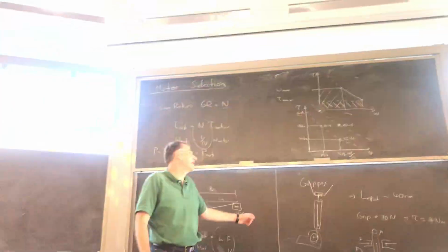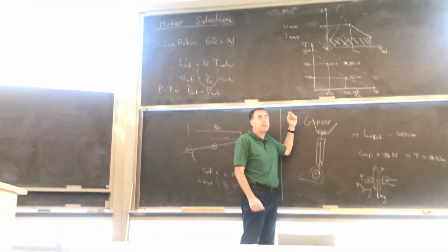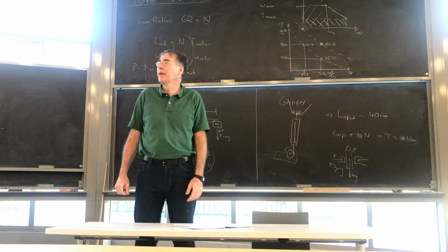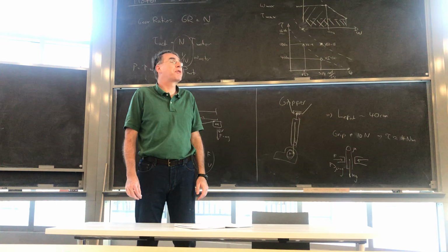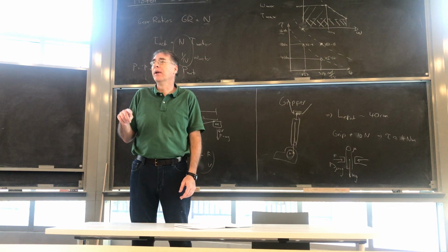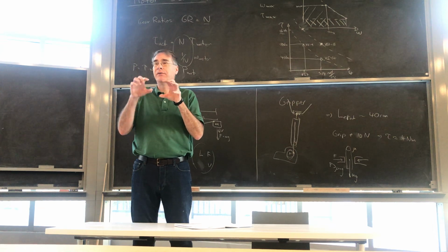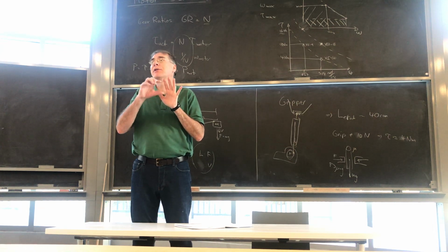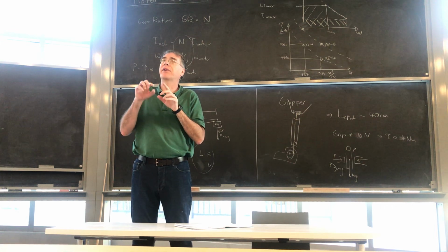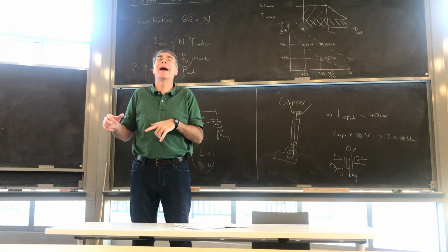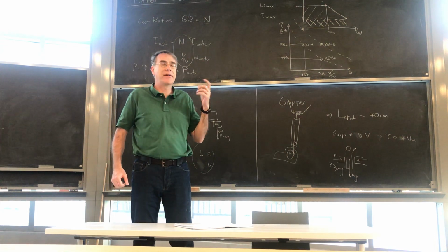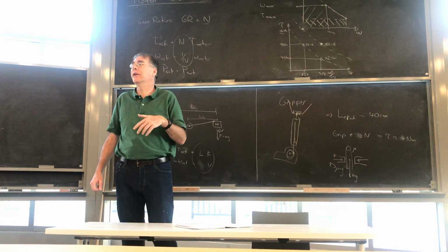But basically, I think of these calculations generally as continuous because you want to hold something, you don't want it to fall. And then the peak gives me a burst when I need it. It has built-in thermal models, so it actually looks at how much temperature is coming. It knows its own, and if you look at the housing, it has all the heat fins and everything on it. It knows the thermal time constants that it dissipates energy in, and so it's got a little model that it runs as to how hot it is. And so based on that, it will cut you off when it needs to. And you can actually, if you look at their status messages, you can see whether or not that caps in.